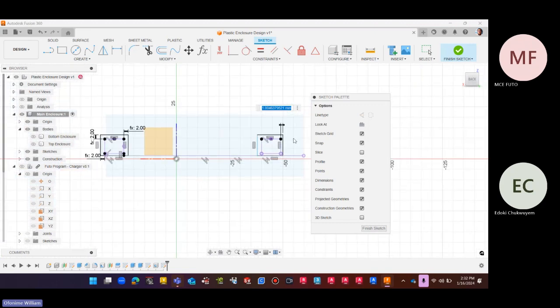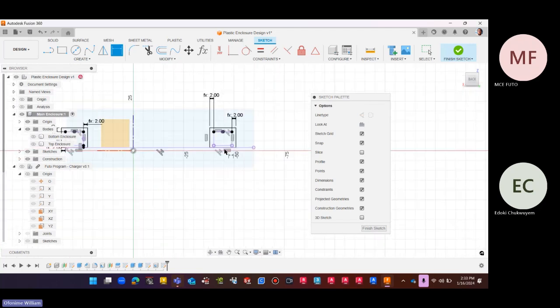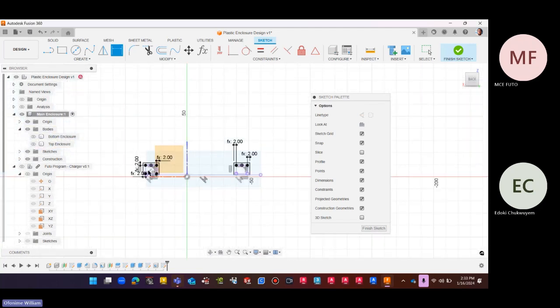This one, me adding shell. Look at what I'm going to do. I just come over to this existing dimension and click. So automatically I have tied this guy to this guy, so once you do an update, they will all update. Same thing here, pull up, same thing, click. Instead of me putting 5, right, I'm clicking on an existing dimension. So now we've been able to settle this as well without going through the headache we did here.